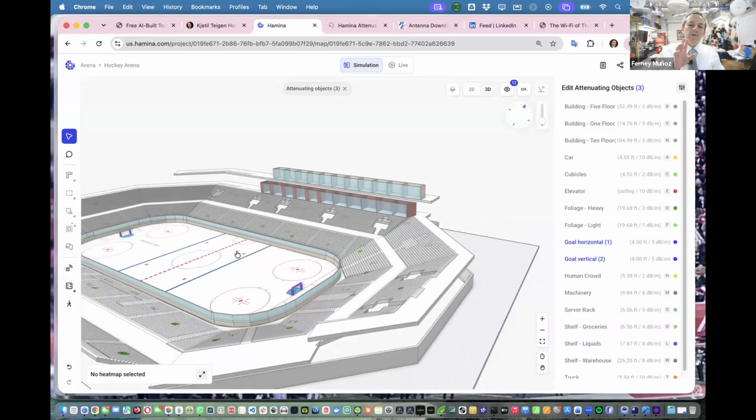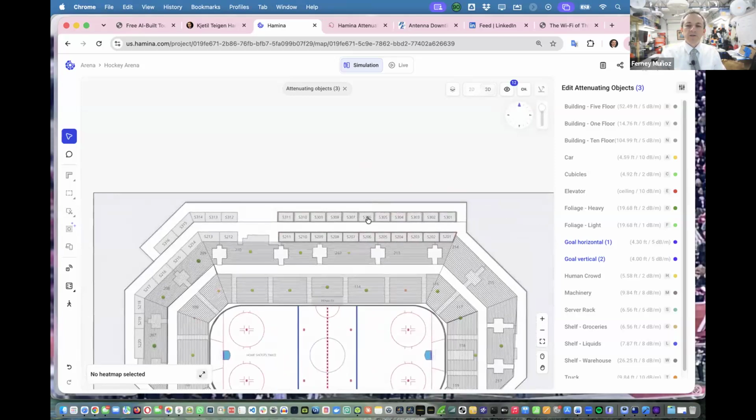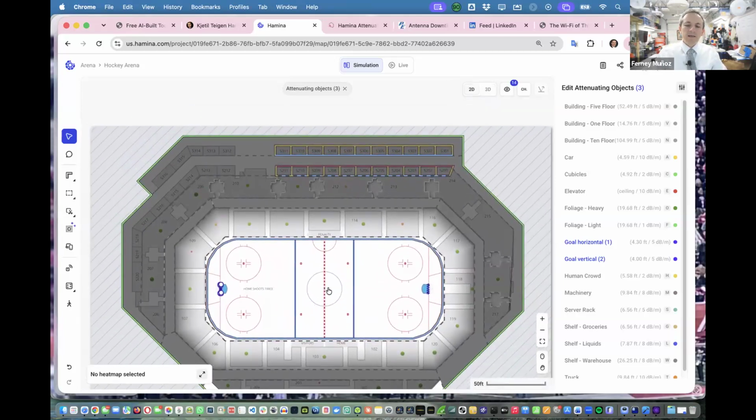This is great. We have another way we're going to do this again. We're going to start from scratch. We're going to grab the floor plan and start making copies of it, floor 1, 2, 3, and 4. And then on each floor, we're going to draw what belongs to that floor, and the rest we're going to cut as a hole in the floor. And we will just do the building, which is going to be way easier than this.